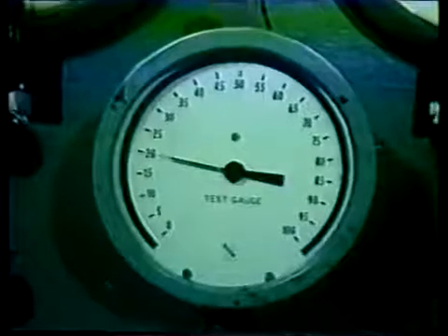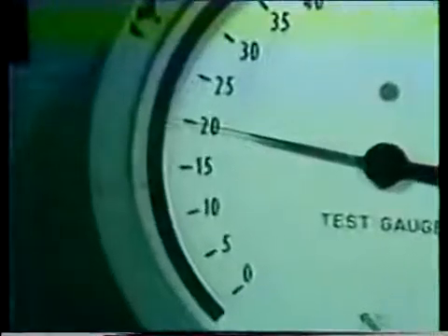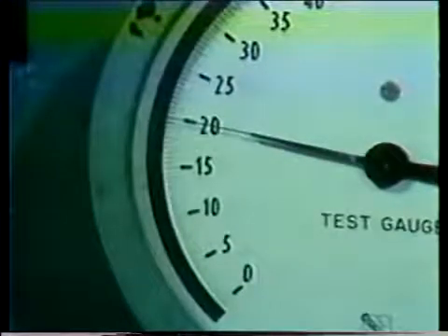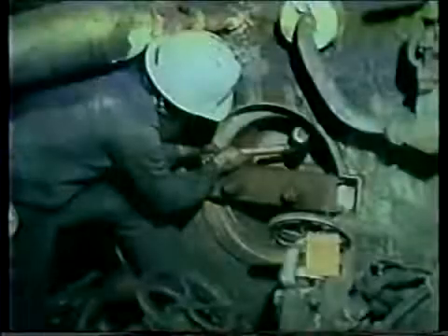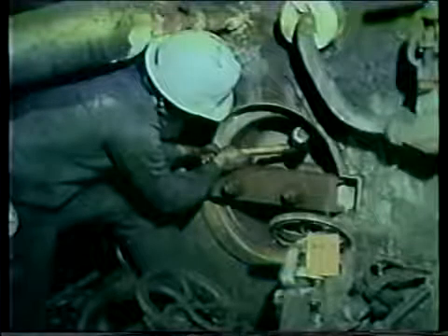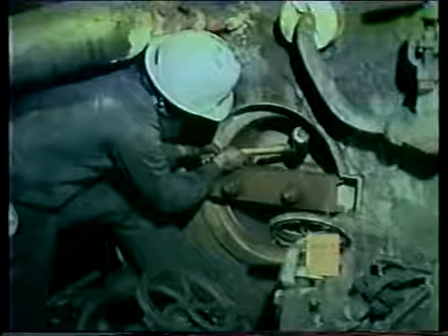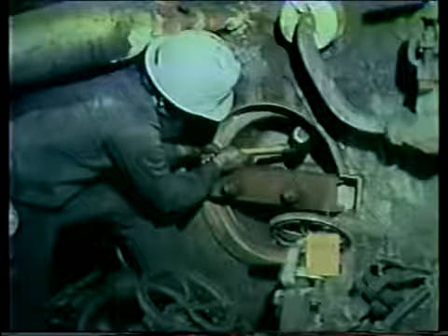Now, we're ready to pressurize the boiler. Increase the pressure slowly by using your plant's condensate booster, or feed water pump. Which one you use will depend on your individual plant. When the pressure reaches about 20 pounds per square inch, or 138 kilopascals, check the manways for leakage. If there is leaking, check to see that the nuts are hand tight. Then, tap the manway cover with a hammer. This will reposition the cover and should even out the pressure on the gasket, stopping the leakage.